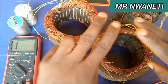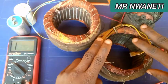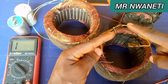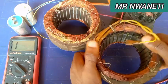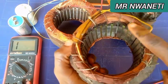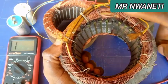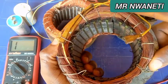Like I've already stated clearly, there are many ways to increase the voltage, assuming the speed is constant. Number one is either you increase the turns from the exciter winding, or you increase it from the main output. So this is the main output.